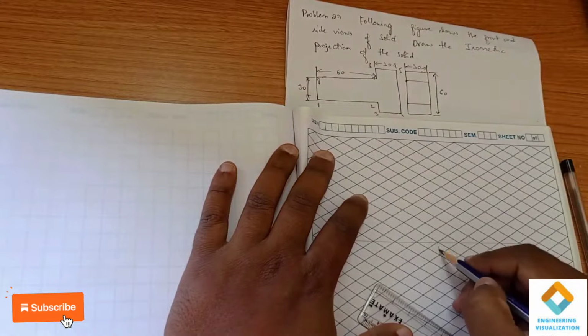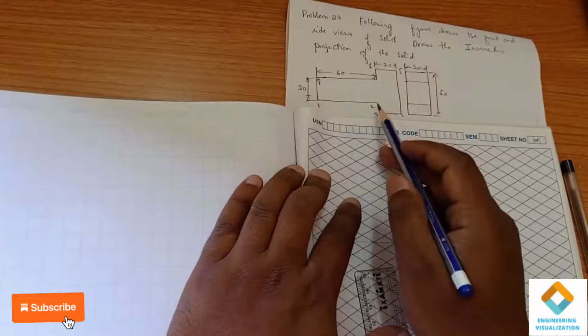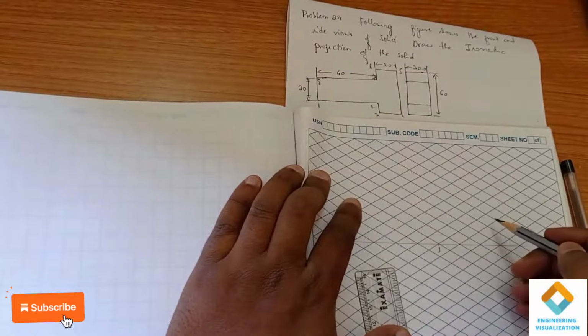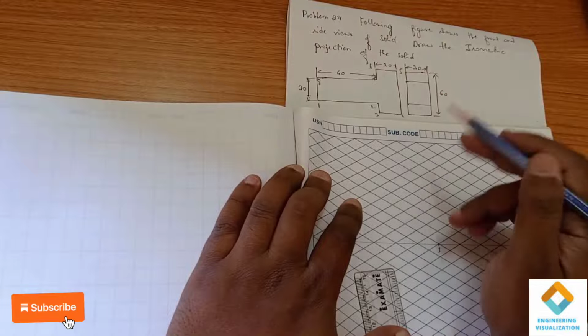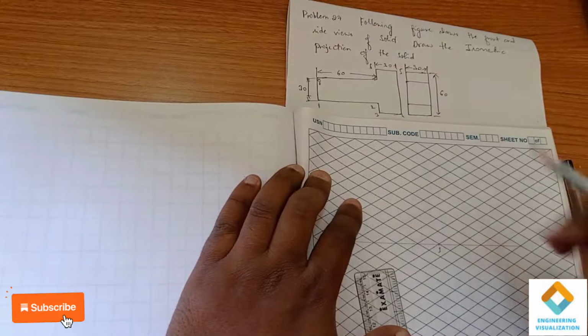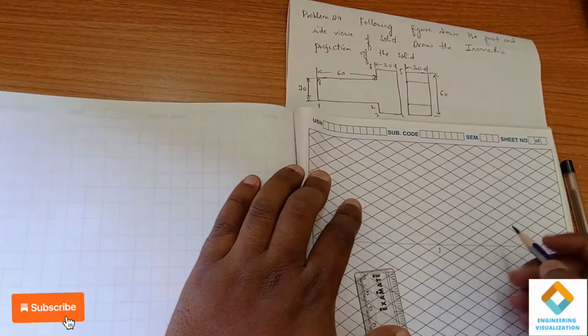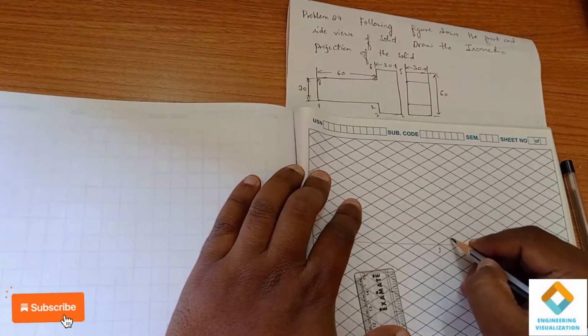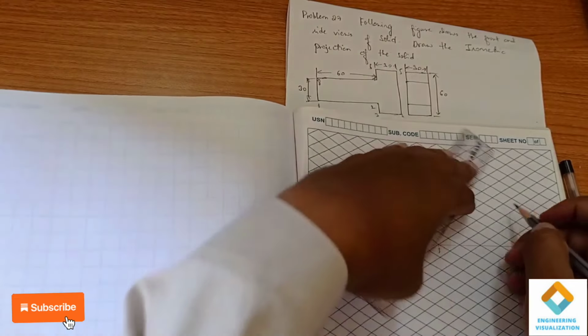From point 1 to 2 we have 60. Remember, horizontal lines will be drawn with 30-degree inclined lines, and the vertical lines, either downward or upward, are drawn vertically only. Vertically straight. From 1 to 2 it is 60, 6 boxes. 1, 2, 3, 4, 5, 6.